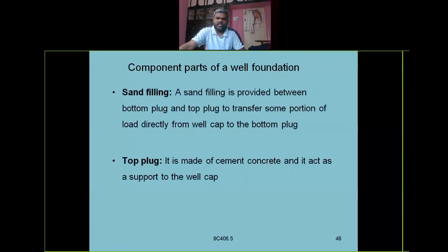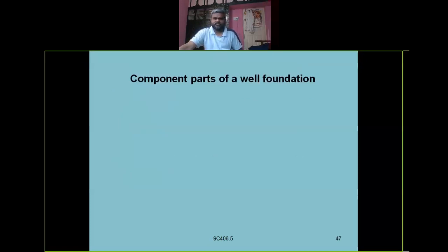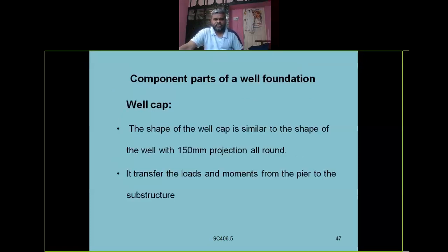Sand filling is provided between the top plug and bottom plug to transfer some portion of load directly on the well. Top plug is made up of concrete. And the next component part of a well foundation is the well cap. The shape of the well cap is similar to the shape of the well with a 150 mm projection around, to transfer the loads and movements from the pier to the substructure.